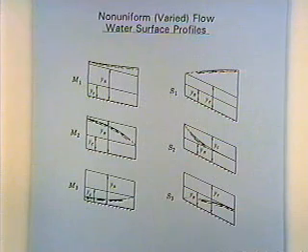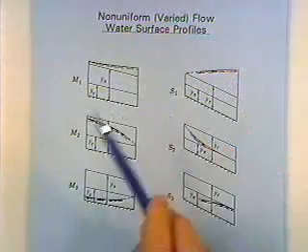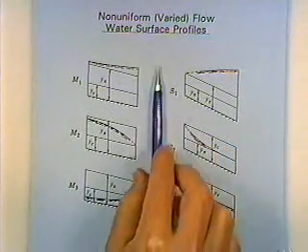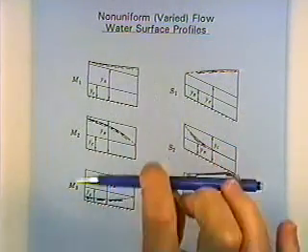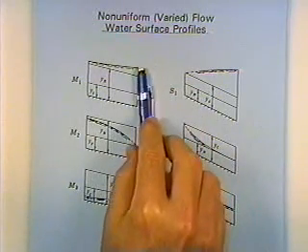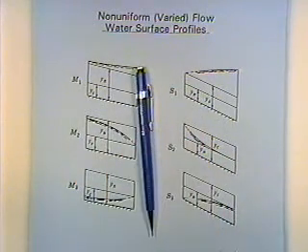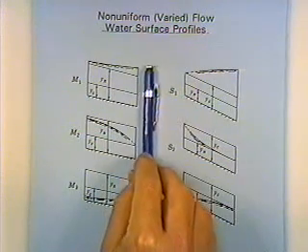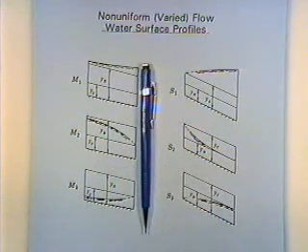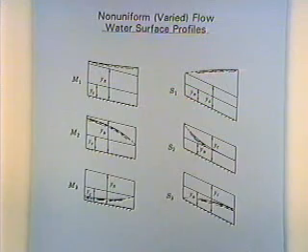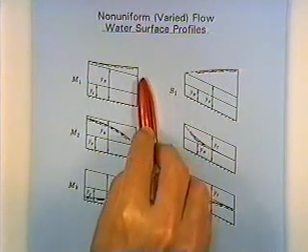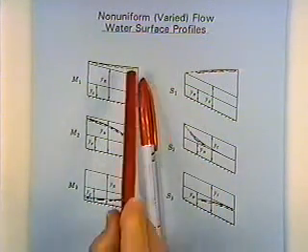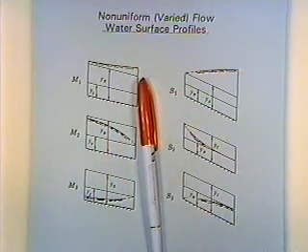Mild and steep relates super versus subcritical flow. Now, in this case, this is called a backwater curve. This means you've got a bridge that's constricting the flow, or you've got something that's constricting the flow, a dam, or something that's causing it to back up. Now, if you've got a mild slope, you've got gradually varied flow. If this happens to be a dam, I'll put this pin here to represent the dam or whatever's backing the water up. It's going to be a smooth transition on back.